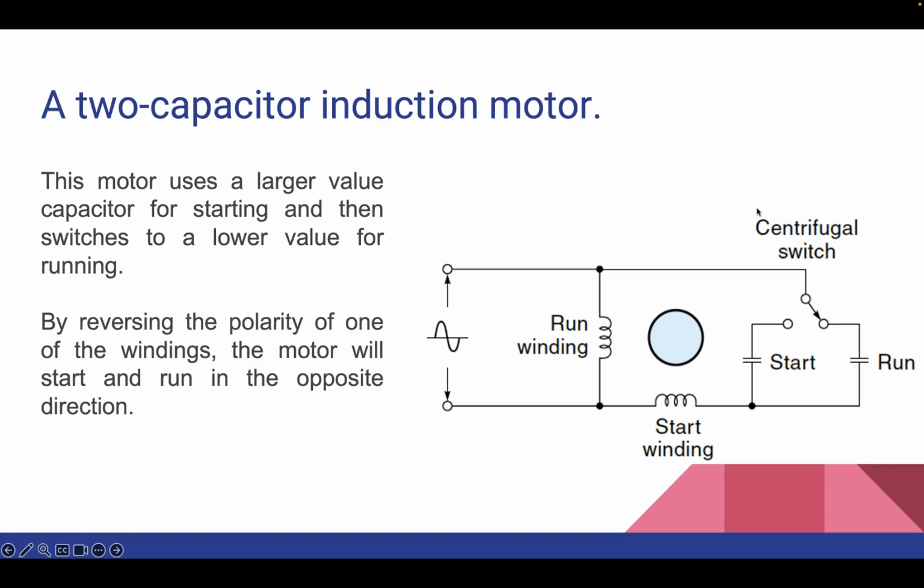Now moving forward is the two capacitor induction motor. This motor uses a large value capacitor for starting and then switches to a lower value running capacitor.